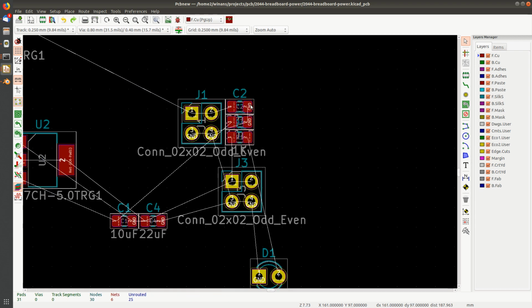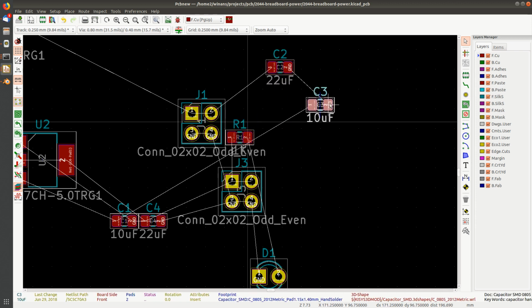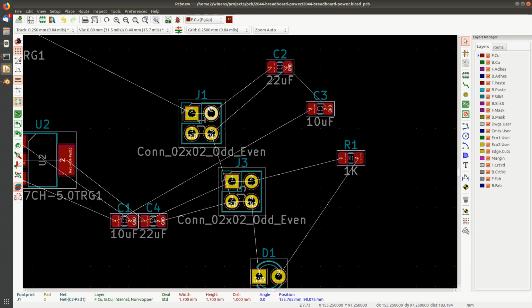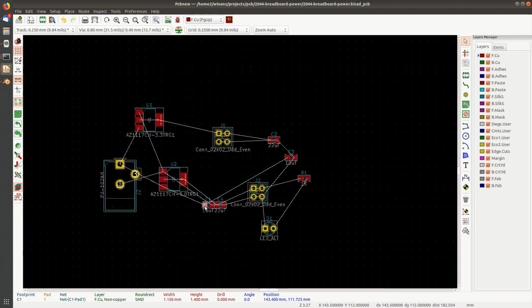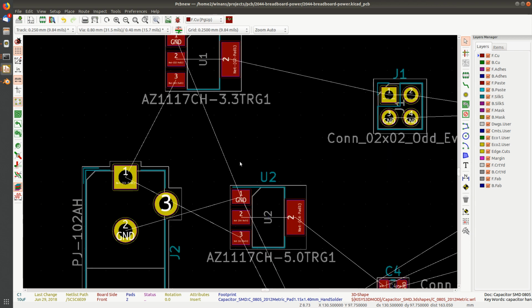Let's just separate these parts around. So I'm going to grab this pin on C2 and just get these things apart from each other. Hit M and move them around. M and move it around there. Hit M on this guy and move them up here so that I can see what the heck these all are. Now, the reason I left the schematic around is because the schematic is not perfectly optimal just yet.